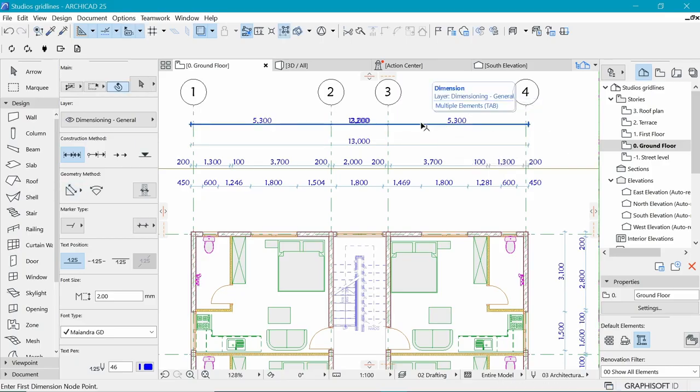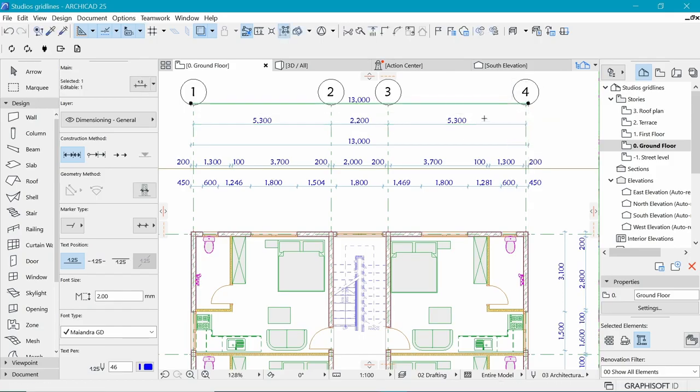And since it's on top of this other one, we want to select the other one and offset it. In order to select it, be sure to hover over there. You can see that the top one is the one which is going to be selected, so tap Tab in order to select the second one. So I can take this one by 800 away.